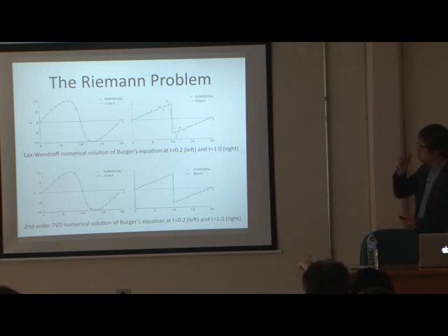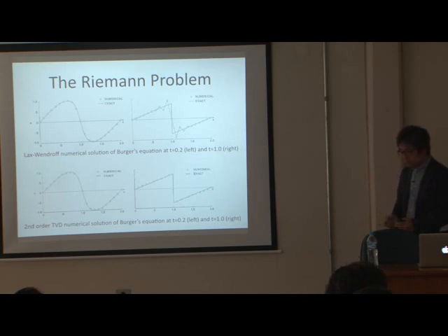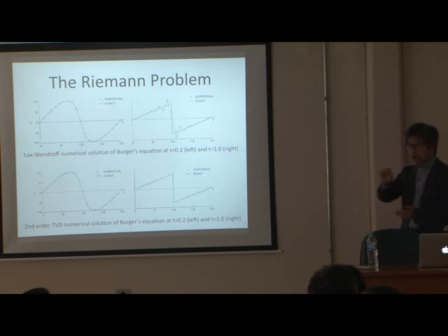In the upper part you have Lax-Wendroff, and the bottom, this is TVD, total variation diminishing. This is one of the flux limiters. How to say? It is a constraint, and this is something like this. This is a TVD term. We say additional viscosity is included here. In this case, the total variation is diminishing. It means that we don't worry about any overshooting or undershooting. Everything is smeared out. So this correction term is counted here, then making for the smooth shock structure.